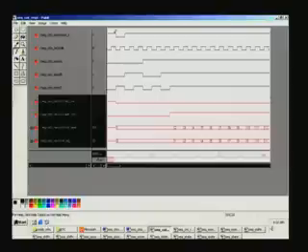So you have a reset signal. When reset occurs, irrespective of the clock edge, you clear the counter as such. This counter reg is here, it is cleared to 0, and you notice that counter next is incremented by 1 right here. So this is what I meant by pre-incrementing, and ABC are in binary progression being the inputs as such, and when ABC are 1 each, that is at this point, then only the advance count goes high, and hereafter once it goes high, then only the counting starts.